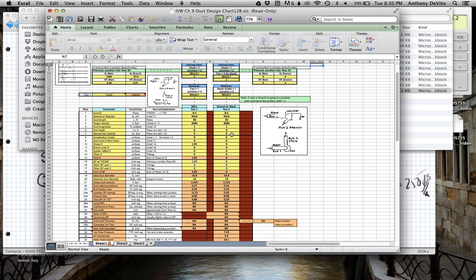On that slot hood, I was saying he's working with some sort of particulate, right? And a particulate is going to be a little bit harder to pull away than a fume is, because you have to carry it in the air. I call that 200 feet per minute across from the furthest point. That was 2 feet to the end of that table. In other words, at the end of that table, I had 200 feet per minute. Yes.